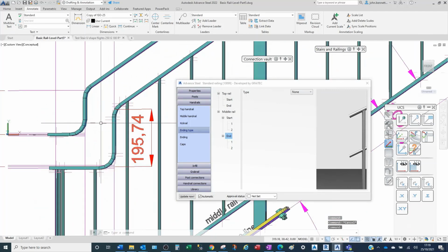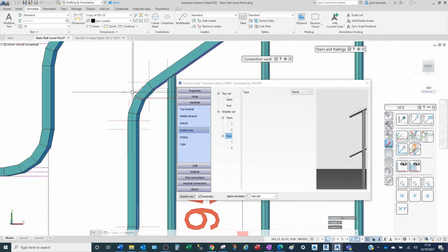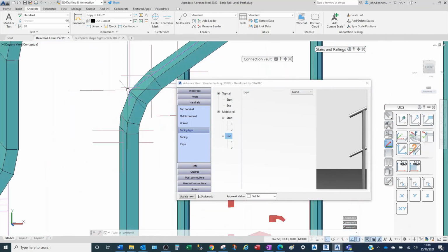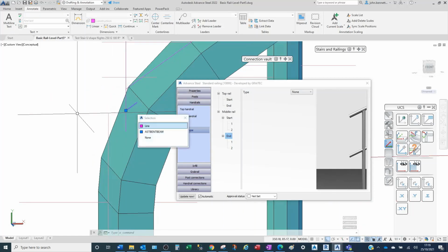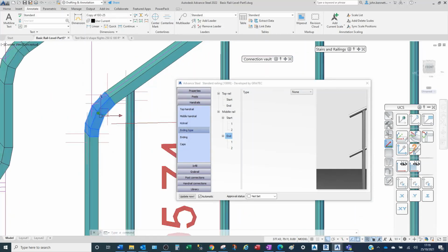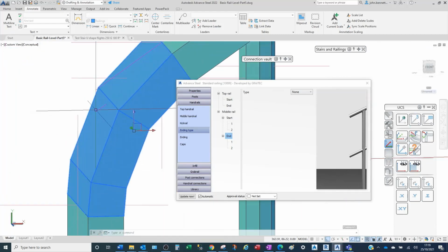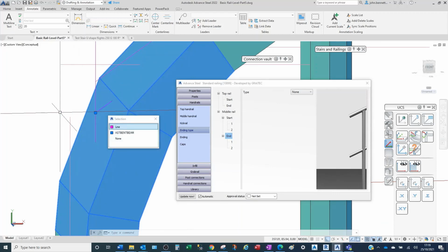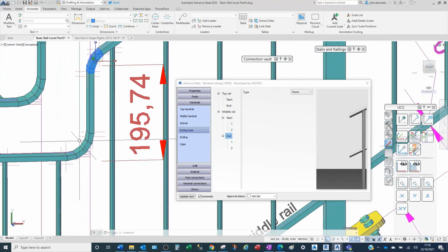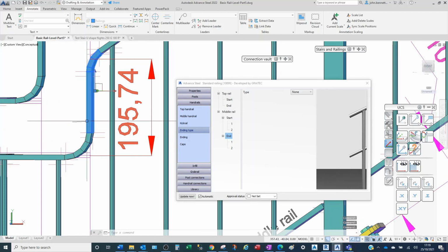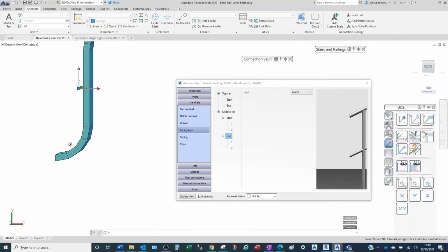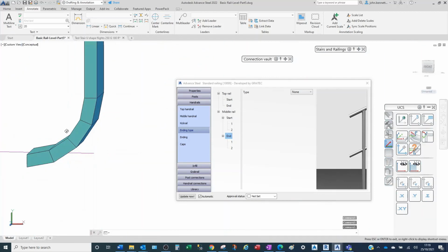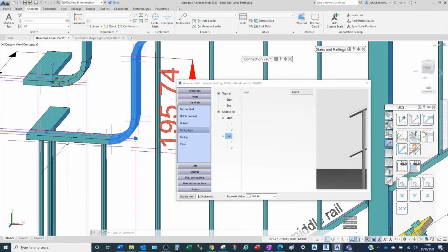The other important thing to watch out for is that when you create a rail, you can see that this is the top of it, and this line here is the middle of it. Although this is a curved element when it's been turned into a swan neck, if you were to miter this rail, you would see it would be working to this middle point here. And correspondingly, where the vertical step element comes down through the rail here, at the bottom, this line is in the middle of the horizontal element returning here.